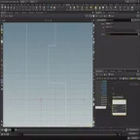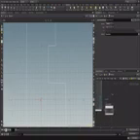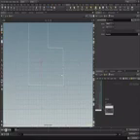This is a detail attribute, and it will give the current iteration number of the for loop. Which is nice, because if we look at our point number and our primitive number, everything is ordered nicely, which means that if we are at primitive number 0, then we are at the second point of this primitive. Same for 1, same for 2, and that's a nice little trick we can use later on.